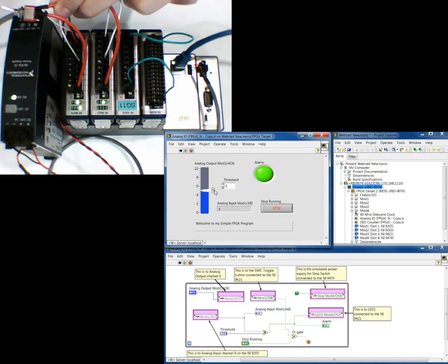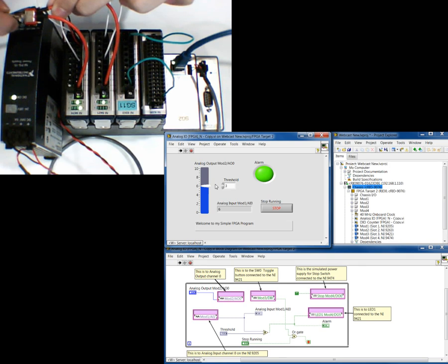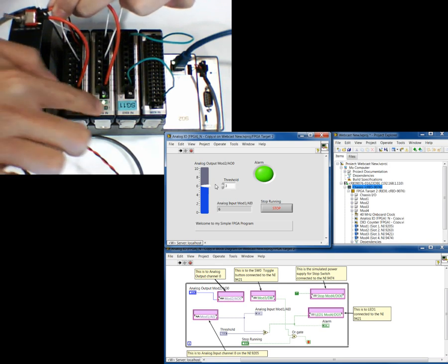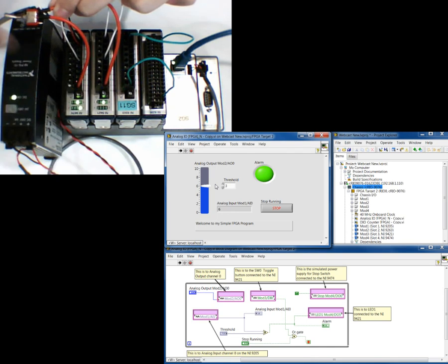You can see that the action has been completed by lighting up the LED. Okay, so now step number 2 is that I'm going to stop the program. The moment I switch off this light, because this light is actually a toggle switch, currently at off position, the moment I switch it to on, the program will stop running, and at the same time the LED at bit 0 of a 9421 will light up. Okay, this is what's going to happen.